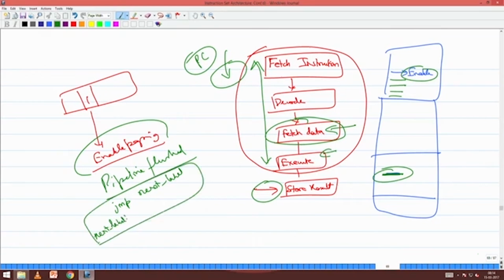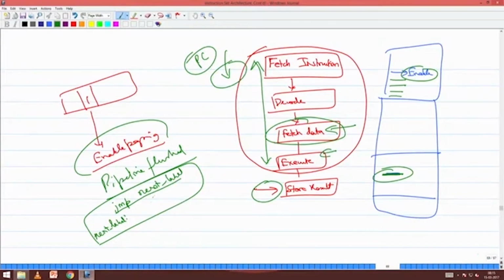Just a statement. So this is an unconditional jump, and the moment I put a jump, there are certain architectures which will flush the pipeline. If there is no prediction, the moment I see a jump, I flush the pipeline. So while the jump can certainly execute, this is PC relative jumping. So this jump will execute irrespective of whether you have enabled paging or not. And even if it executes, it will just go to the next label and it will not do anything. And after that, obviously, paging gets enabled anyway.